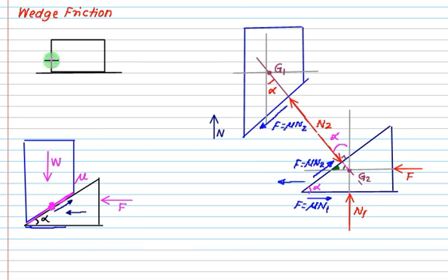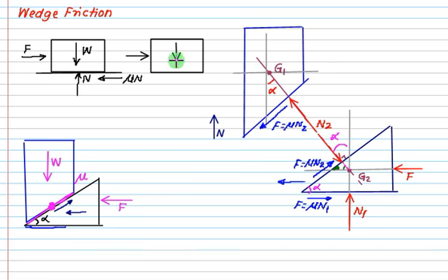So we'll come to the basic idea about the friction angle. If this is the weight W, this is the normal reaction N, and this is the external force applied F. So the friction force will act like this, and this value of friction force is mu N. So if I draw the same figure like this, I have one force like this, one force like this, and can I combine these two forces using vector as this force?